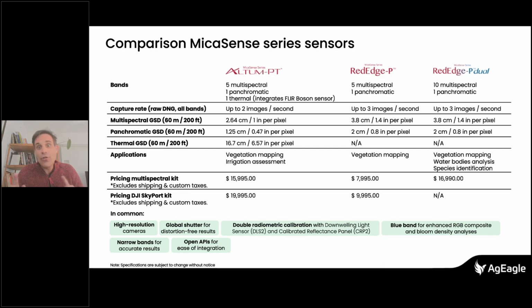And even not do the pan sharpening, depending on what you really need it for. If you want to do spectral analysis of the images, what I personally recommend is to use the multispectral images without the pan sharpening, because the reflectance values may deviate up to 5% after pan sharpening, right? Because you're going to mix it up with a grayscale image.